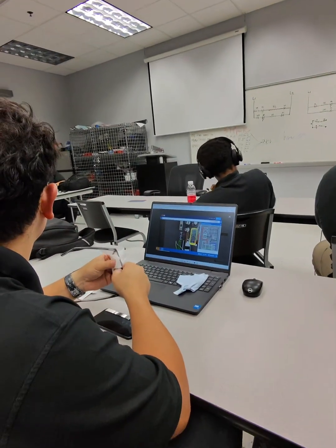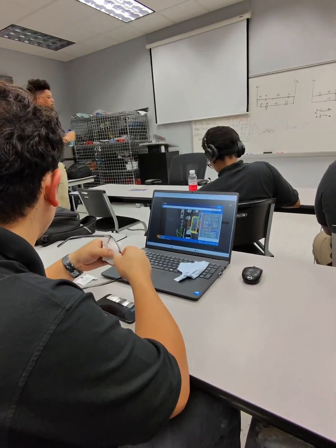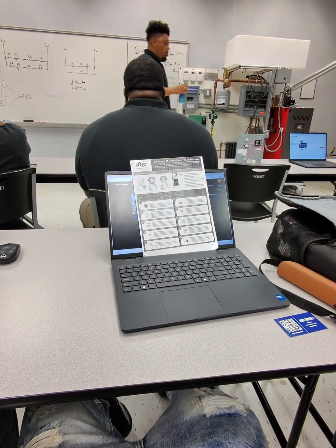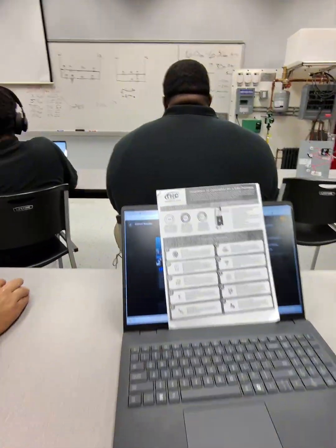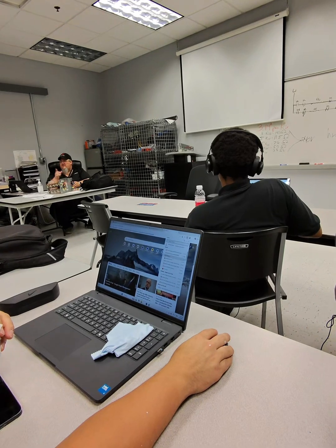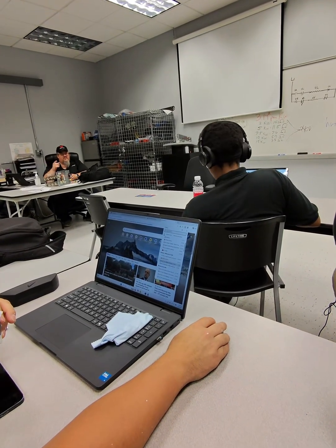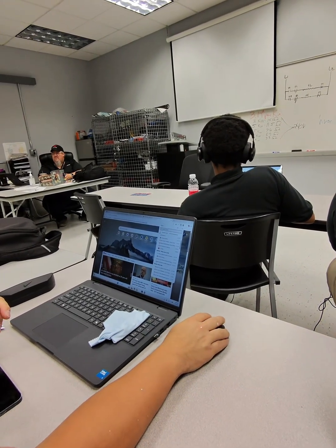What are some of the safeties that you have on the furnace that it goes through before it brings on the induced draft motor? Pressure switch and rollout switches. Good job.